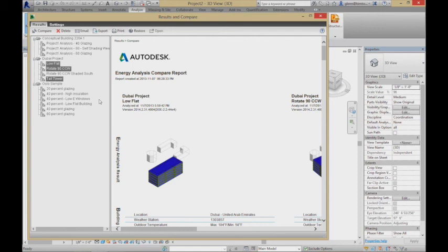From the standpoint of wanting to understand the effect of the shade that the other buildings are casting and cutting out some of the sun, you'd want to include the form just so that shade would block the solar radiation. It's really just at that level. There's not a notion of the other buildings actually releasing heat, so we can't think about the overall microclimate and whether that's being heated up by the building. But the shading provided by the other buildings, or the shielding from the wind, that's considered.